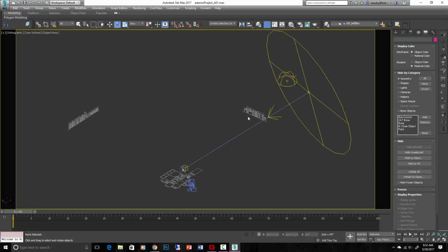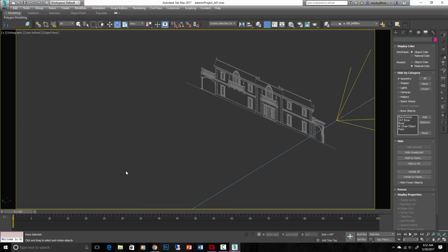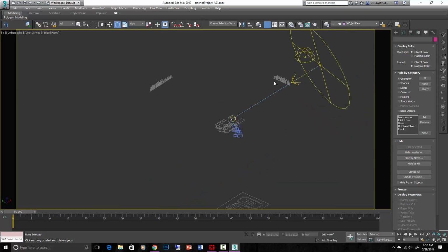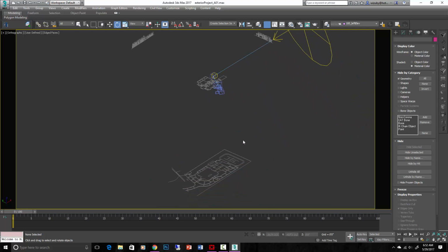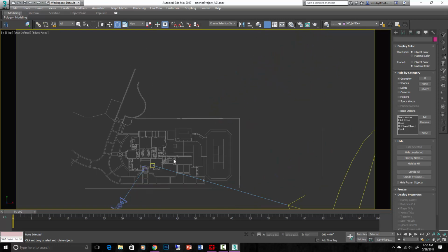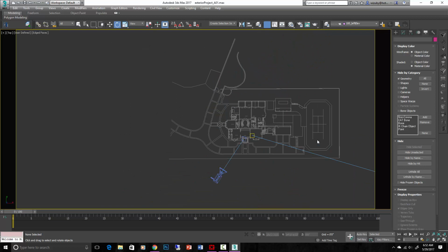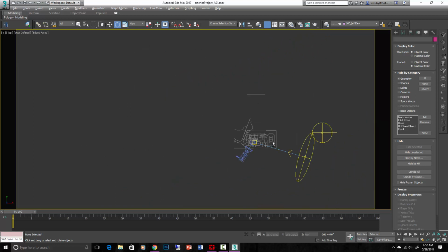If you look on the side, the other elevation I had to make, I took that left elevation and put it way over there to the right. And I usually put them on a layer and freeze them. And then I have the site way down here and the floor plan here. So when I look from the top view, I can see them straight on. It's as simple as that. You set them up in orthographic projections.